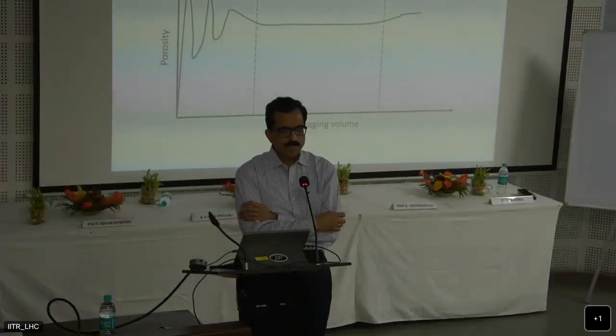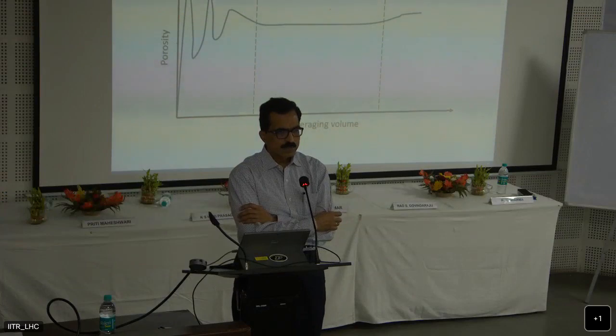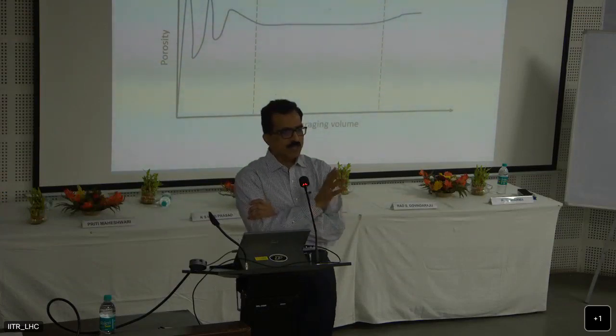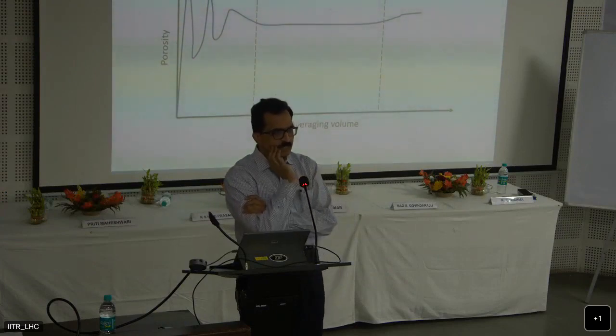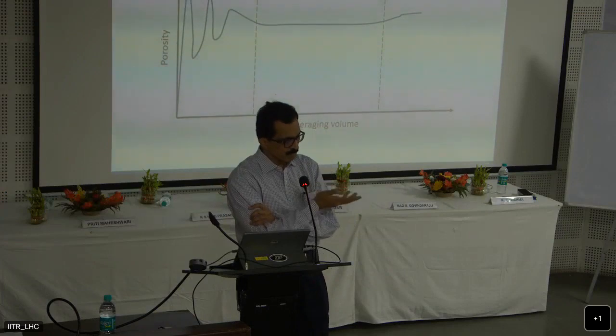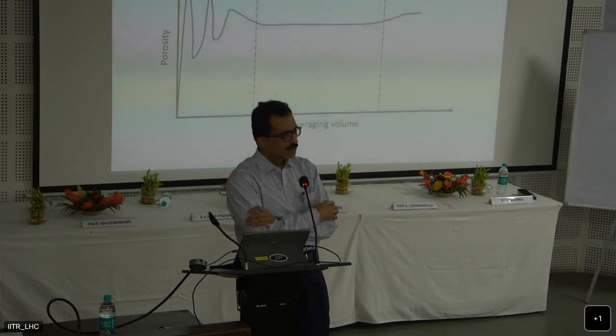One location, other location, Kx1 and Kx2 are not equal, then it is heterogeneous. If the porosity is changing, then it's also heterogeneous. So if properties are changing in space, then it is heterogeneous. And if that needs to be represented, then we would represent it as a heterogeneous aquifer. Not sure I'm answering your question.